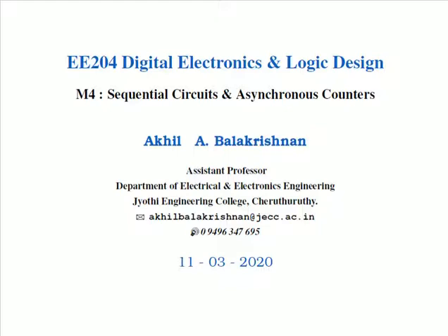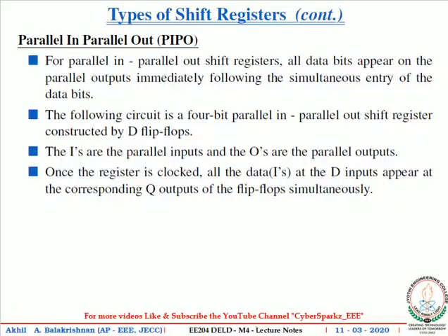Module 4: Sequential Circuits and Asynchronous Counters. Today we are going to study shift registers. In the last class we have already seen the first two shift registers, serial in, serial out, SISO shift register, and serial in, parallel out, SIPO shift register. The next one is parallel in, parallel out, the PIPO shift register.